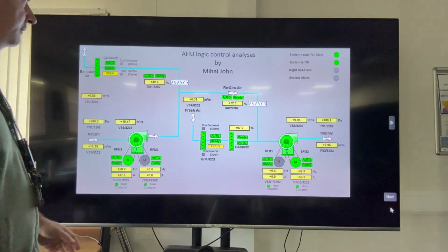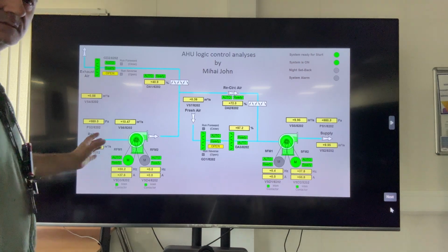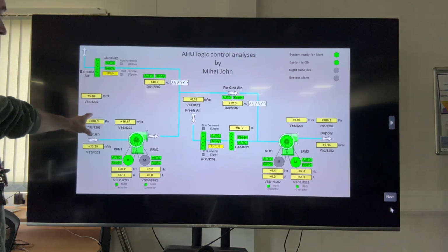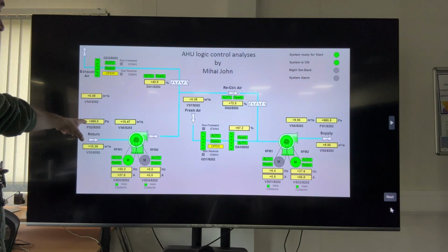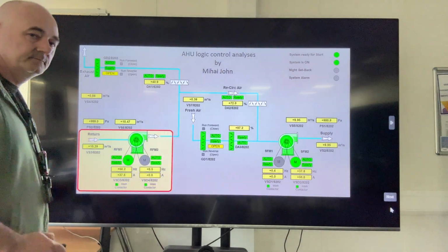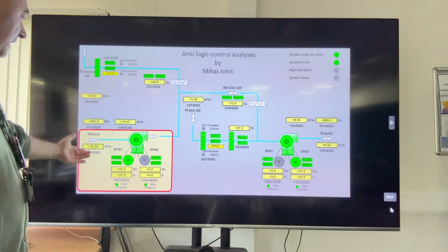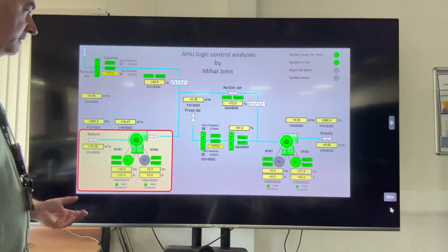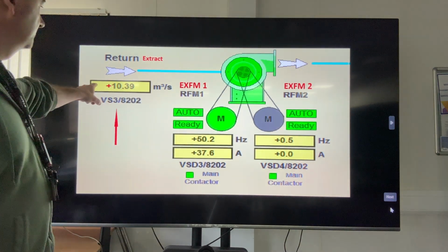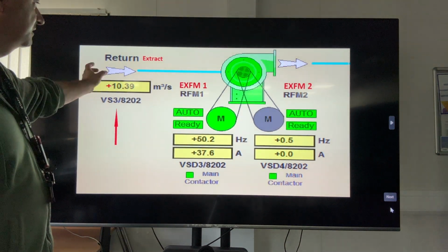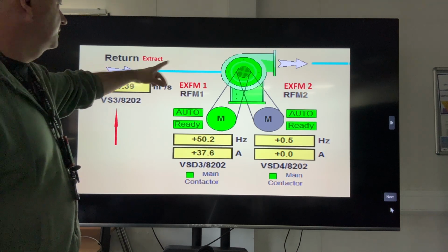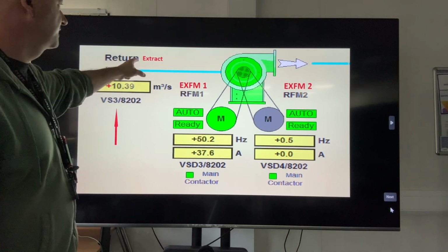So this page will show you how our AHU works. If you look here, on the return, I have negative pressure represented as positive pressure. I identified this 4 years ago. I raised the problem, and if you zoom in, you'll observe that this is positive, but it's supposed to be negative, and this fan should not be called the return fan, but the extractor fan.